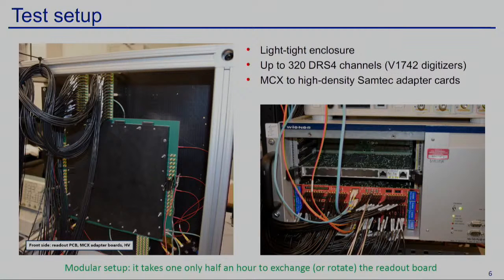So my next slide. This is the rear side. The LAPPD is sitting behind this PCB. The PCB is custom made. These are the adapters from high-density connectors into MCX cables and then to the digitizers. These are conventional V1742, and we have 320 channels.